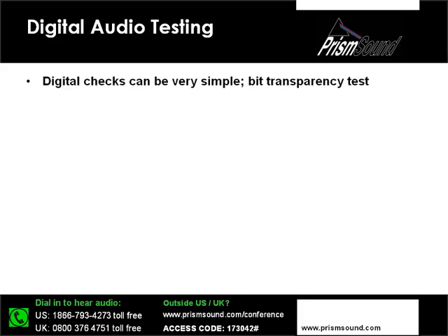As I say, it's quite straightforward to test a digital audio device that's supposed to handle digital audio transparently. We don't need to concern ourselves with making frequency response measurements, noise measurements, distortion measurements, crosstalk analysis. We can do effectively all of that in a very simple test by just ensuring that bits in equals bits out. In other words, the digital audio has not been affected in a negative way by the device that we're testing.